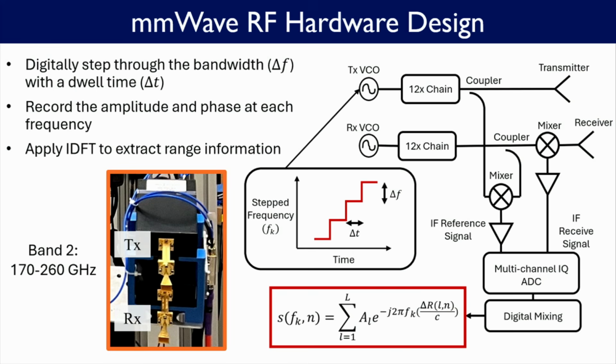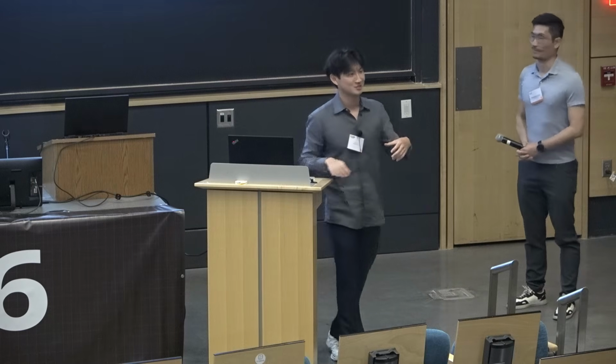Yeah, this one. So we have a stepped frequency setup instead of a continuous wave setup. And then your second question was about range. And so that's what we're getting to. The reason we have kind of a foot-by-foot scene is because of the beam width of my radar. The maximum range of the radar is 20 meters, something like that. We expect that it should work, and we have some simulation results in the paper that take into account path loss, and these things are built in ray tracers, so I think that would be of interest to you. Yeah, this thing does generalize to long ranges, I would expect.